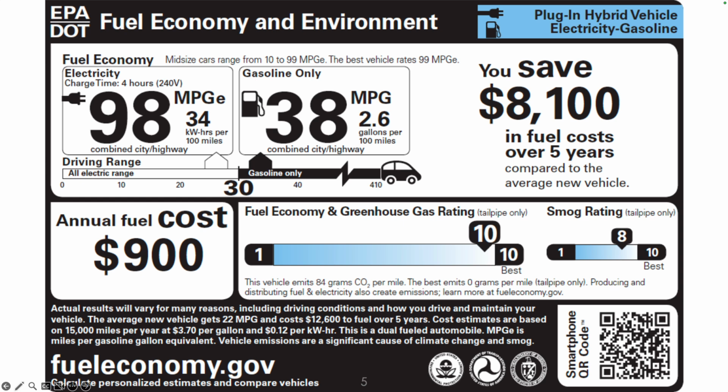And then there's actually an electric efficiency that they term MPGE. That stands for miles per gallon equivalents, and we'll talk in a lot more detail about how that number is calculated in a second. And because of the counterintuitive nature of being able to calculate those fuel consumption metrics, they do that for you, and they give you this estimate of how much it would cost on average for you to pay for fuel over the course of a year, so that consumers don't actually have to do the math to understand what those consumption numbers actually look like.